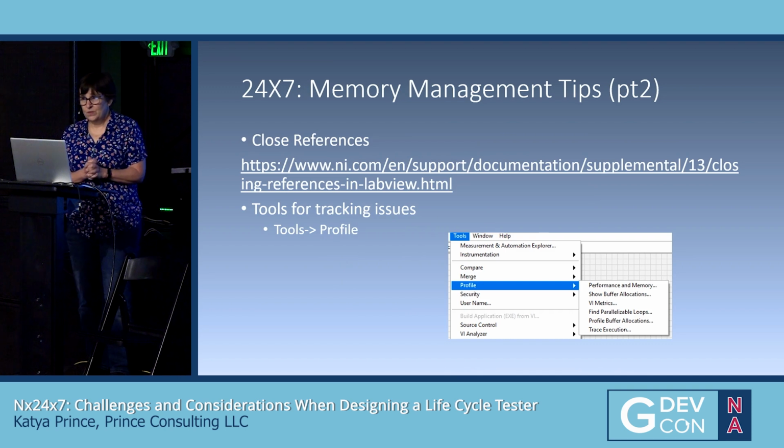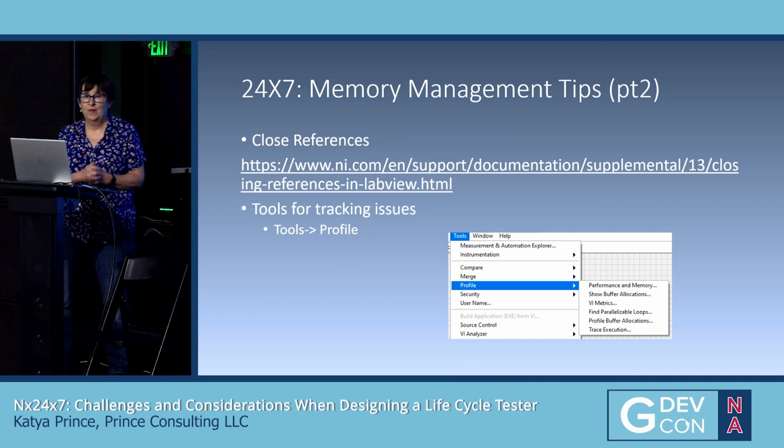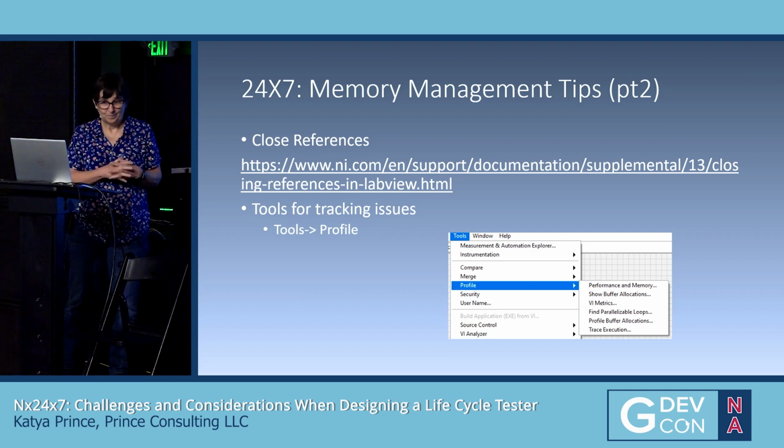The other thing you need to do is to keep track of your references and make sure you're closing them if you're doing a lot of VI server type work. I never remember which ones you have to close and which ones you can ignore, but luckily when I was writing this talk, I came across this NI paper that lays out, these are the ones you need to worry about, these are the ones you don't need to worry about.